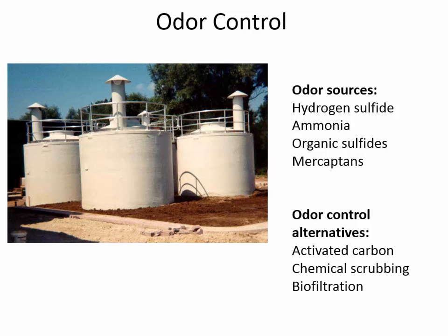I mentioned earlier that sulfur in the wastewater tends to increase the odor problems associated with a trickling filter. And so especially if you have an active blower in place and you're forcing air up through the filter media, then that can really spread pretty unpleasant smells into the surrounding areas.